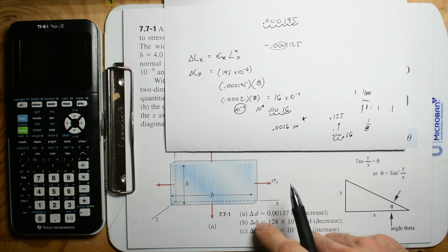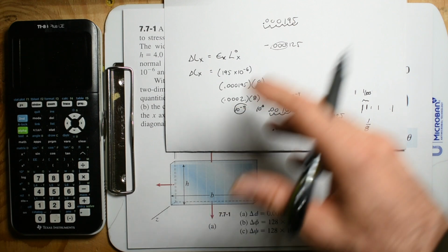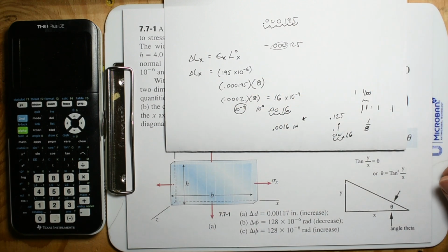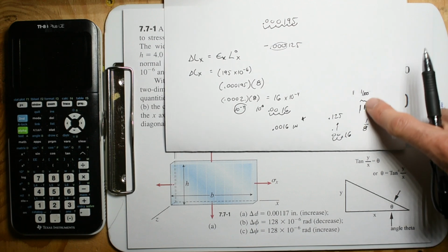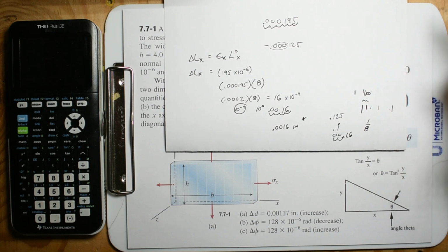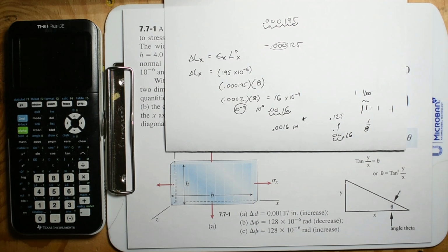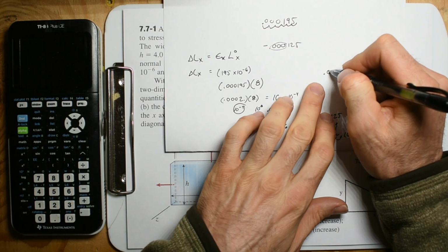I mean, you can't just say 10 to the negative 4 and compare it to 10 to the negative 5, and 10 to the negative 3, without actually having something to gauge it by. And even that's a pretty crap gauge. What's a hundredth of an eighth of an inch? All you're saying there is, well, that's pretty small. So machinists work in thousandths, which is only this.